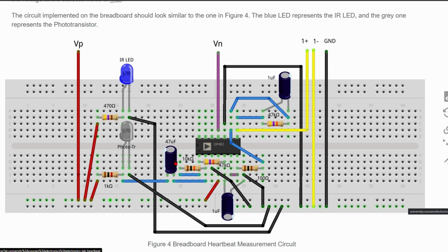There is an issue though with this capacitor. It's actually facing the wrong way. The capacitor's long lead, or the side that doesn't have the negative on it, should be facing the other way. So it should be going to the right, not to the left. So if we turn that around, then we should be okay. Now, I still have a problem with my circuit, so I'm going to actually go through and debug it step by step, and we're going to see this as well.